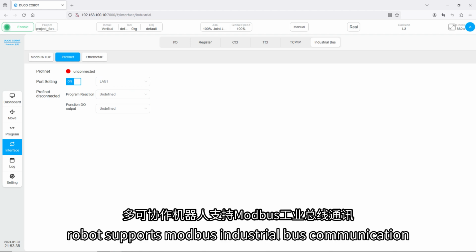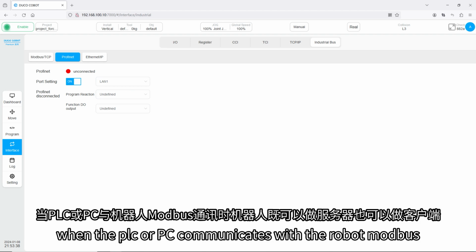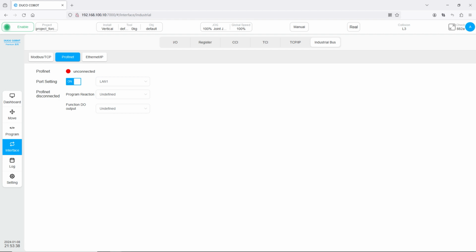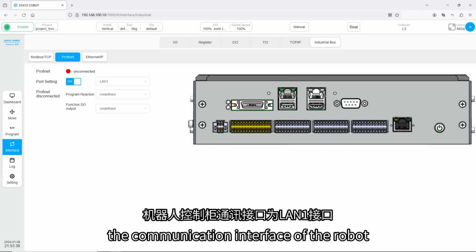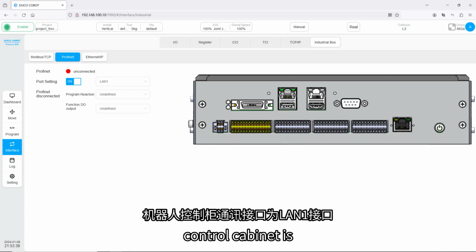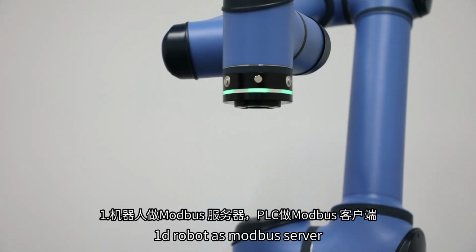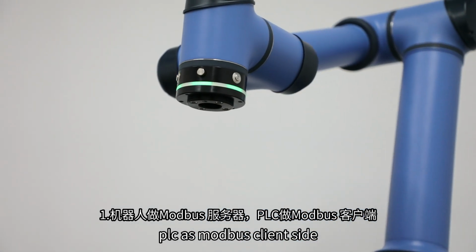The multi-collaborative robot supports Modbus industrial bus communication. When the PLC or PC communicates with the robot via Modbus, the robot can be both the server and the client side. The communication interface of the robot control cabinet is a LAN interface. Here, the robot is the Modbus server, and the PLC is the Modbus client side.